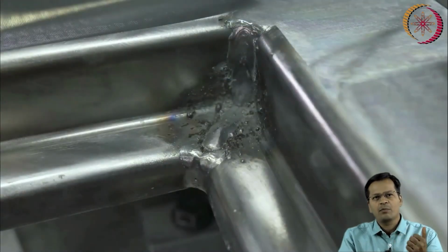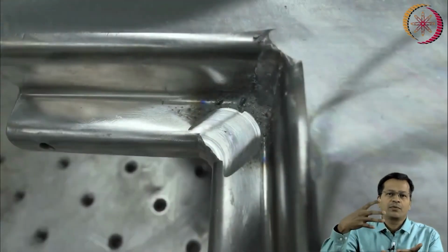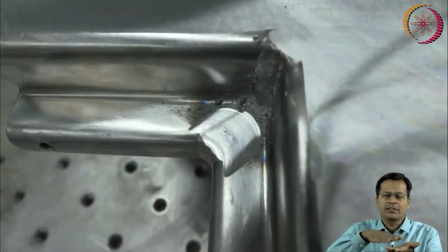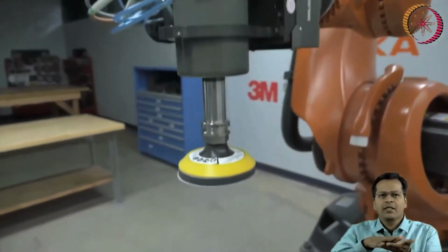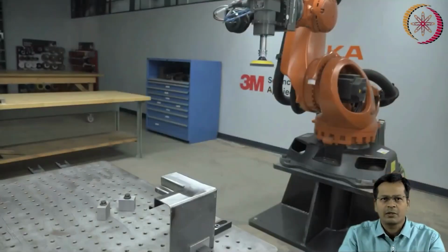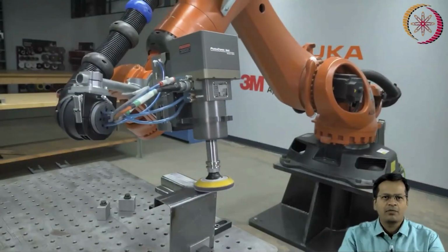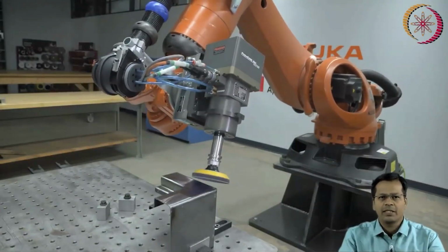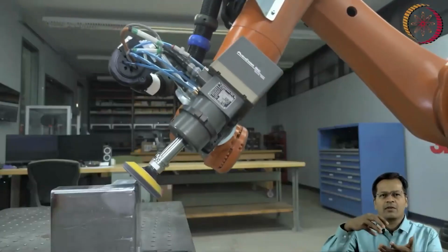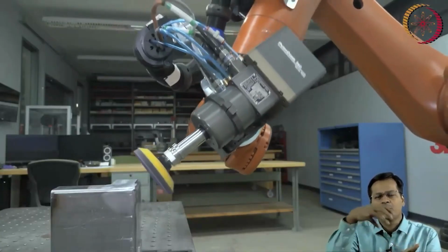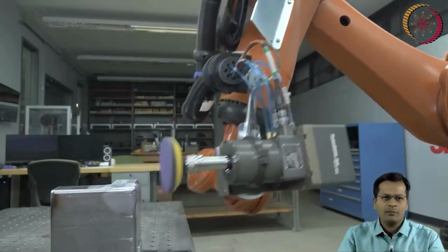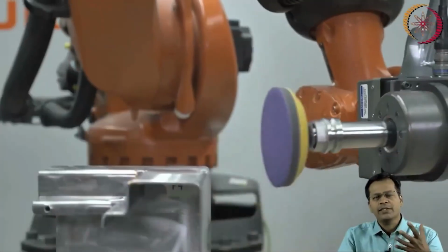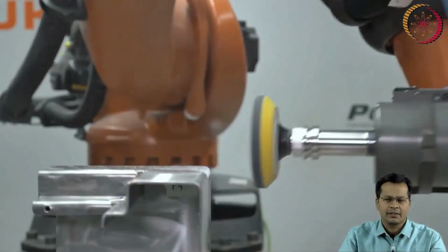In this type of robot, normally it is fitted also with a force sensor. It can feel the forces, right, so that it can have a constant force all over and do uniform grinding on polishing operations. So this is the type of deburring, and finally polishing will be done. Each process requires a different tool to be fitted at the top of the robot, and each one does its own job. Finally you get to see a uniform finished thing, right?